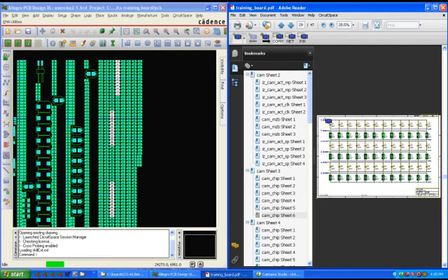You can also hold a control button down, which will toggle the current state of the elements that were selected. So you'll see that I'm selecting 4 elements that were not selected prior and 4 that were selected. And this will toggle the state of all 8 elements. If you click within the Adobe Reader, it resets the selection set.